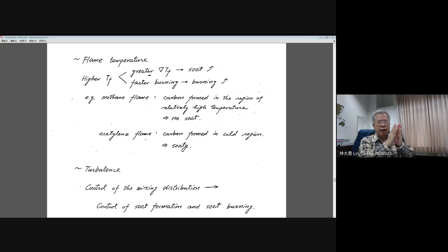They can nucleate the soot a little bit away from the diffusion flame, and they have less supply of oxygen from the oxidizer side. You will have a larger soot formation. Those factors give a good chance to promote soot formation. Then you will have a sooty flame.